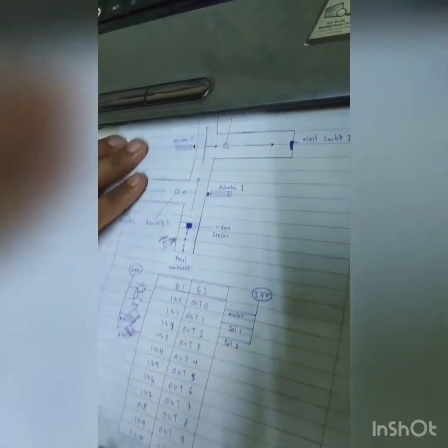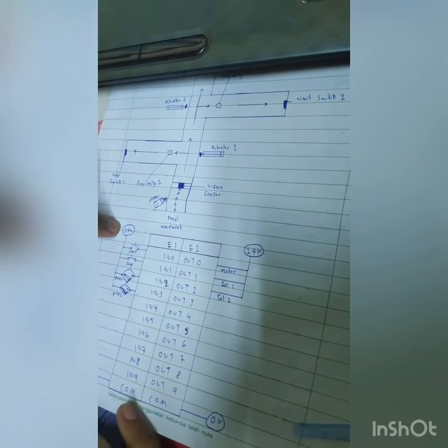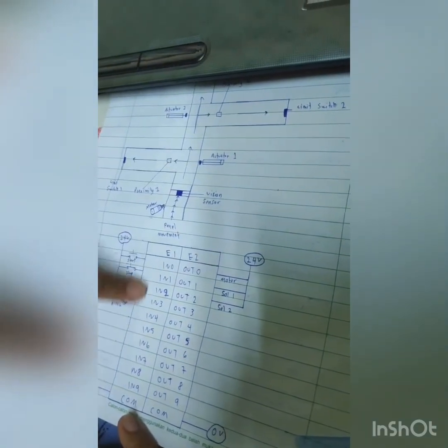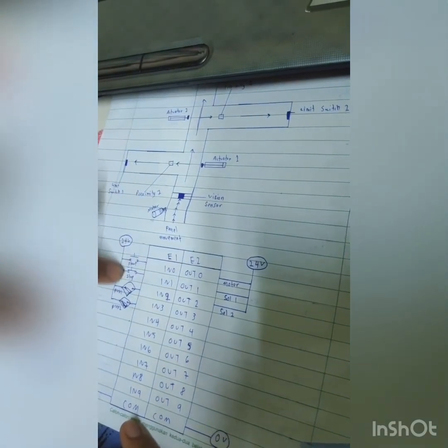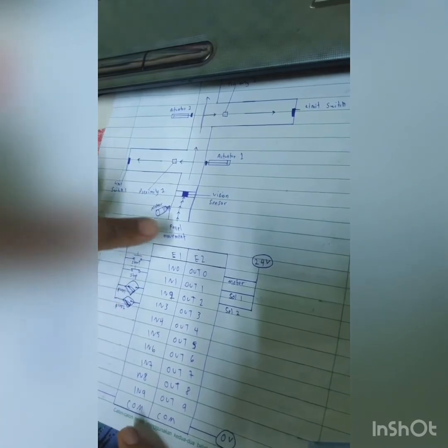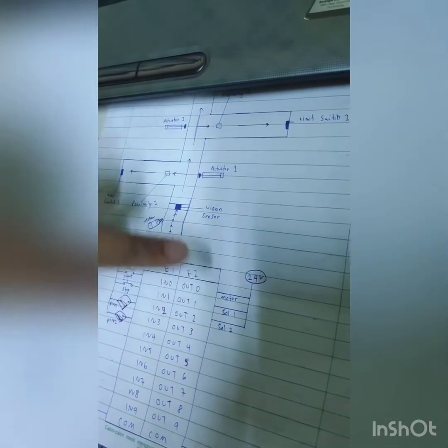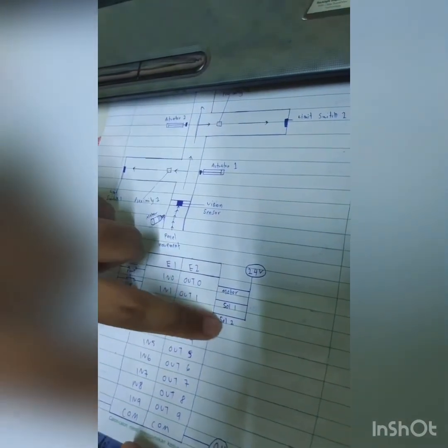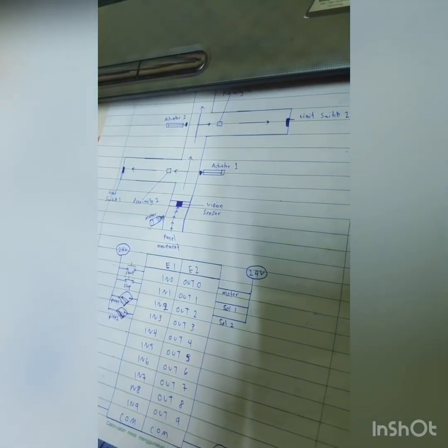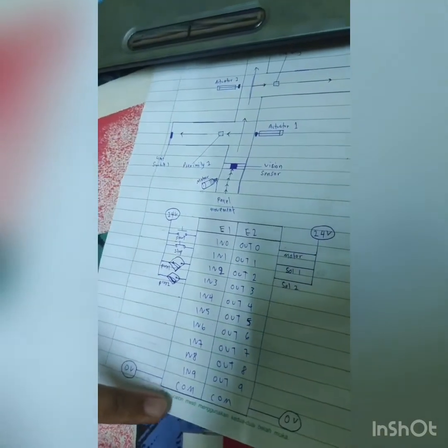Okay, now we go through the wiring diagram. At the top we have 24 volts. On this side we have four input components: start and stop push buttons, and the proximity sensor, and for the output we have the motor, solenoid 1 and solenoid 2. Solenoid 1 is attached to actuator 1 and solenoid 2 is attached to actuator 2. And finally we have 0 volt connecting to the COM.